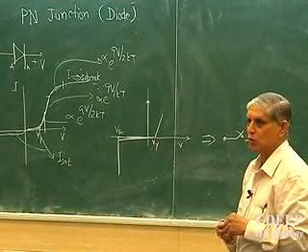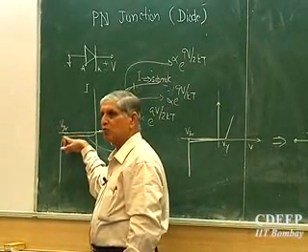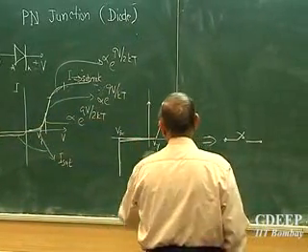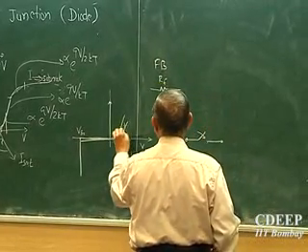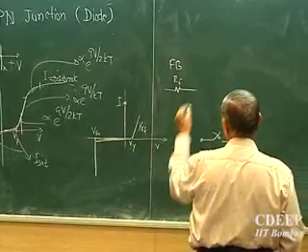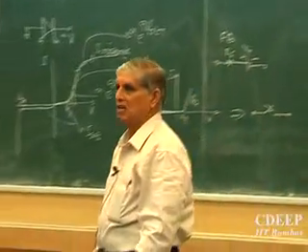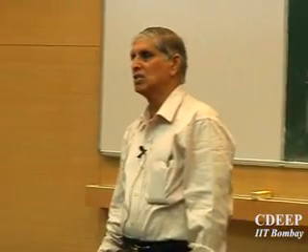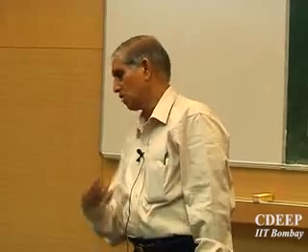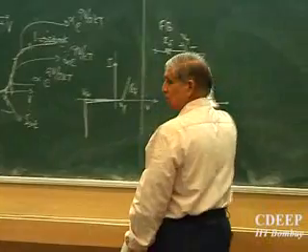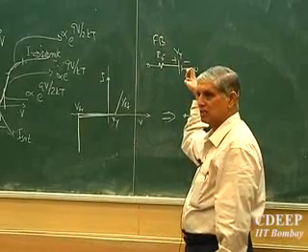We can also give some slope here, because the current, though it looks as if it is constant, is not. It is increasing in the negative direction, but very slowly. So equivalently, in the forward bias, if this is the slope of this characteristic, then the diode is an RF plus a cut-in voltage. A diode can be represented as a small battery of V gamma, because unless V gamma is reached, RF is infinite, and when V gamma is crossed, the current starts moving. So this is the equivalent of a diode under forward bias.